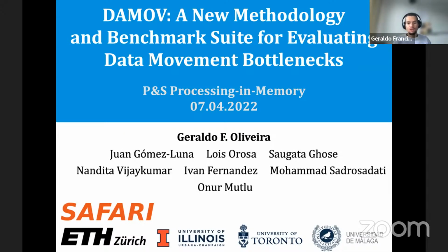You use both out-of-order cores and in-order cores and accelerators in your data movement evaluation in this paper to evaluate data movement bottlenecks. And the in-order core setup is really similar to the UpMem setup. So we have simple in-order cores connected to some scratchpad memory. In this paper we use caches, and also a memory channel that provides high bandwidth for the NDP in-order core. So in that case, it's quite similar.